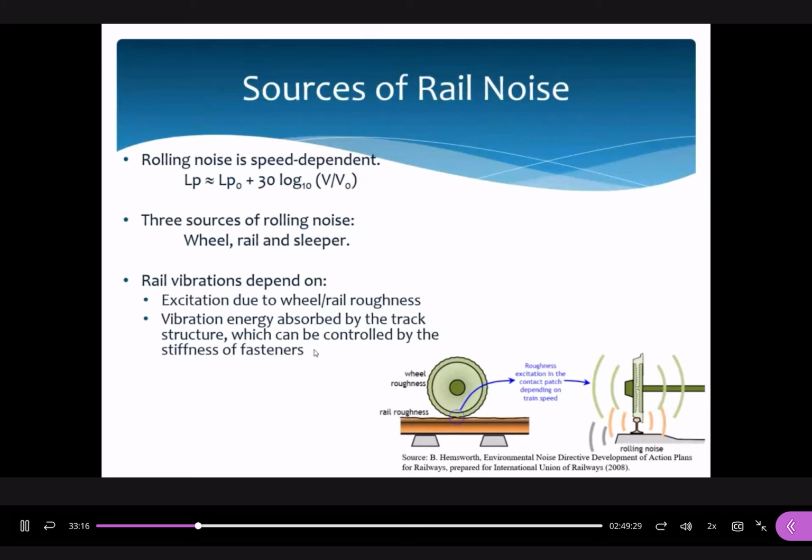Although we apply an external force to the system, if we do not have any force that can be transmitted to the structure, if Ft is equal to 0, it means that we can well control the dynamic effects, correct? So when you take a look at this figure, this is when the ratio Ft to F is equal to 1. What does it mean? It means that when you apply 10 Newton force on this structure, 10 Newton could be transmitted to the ground floor, correct? So we want to make this ratio as small as possible.